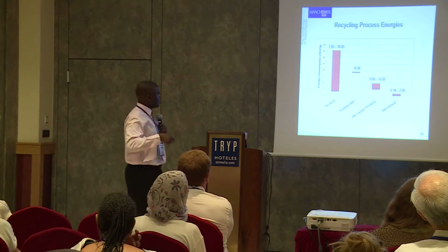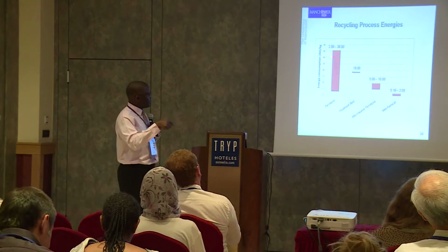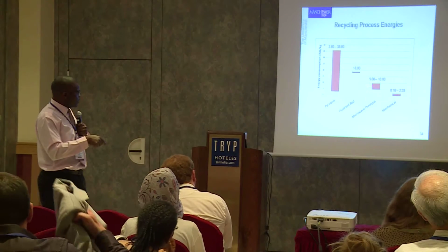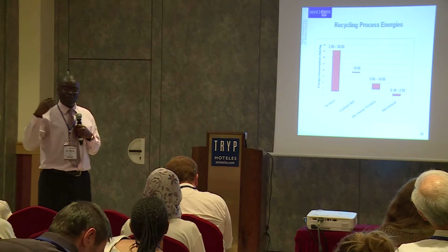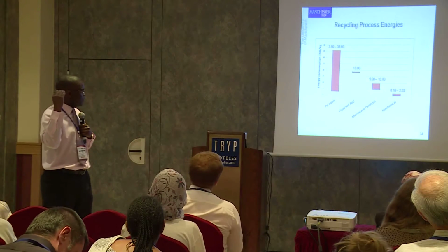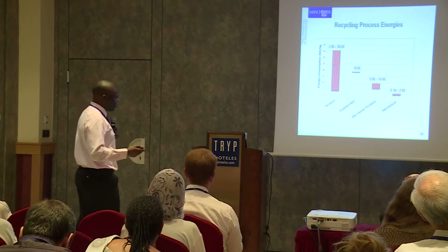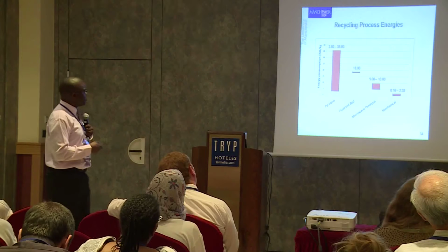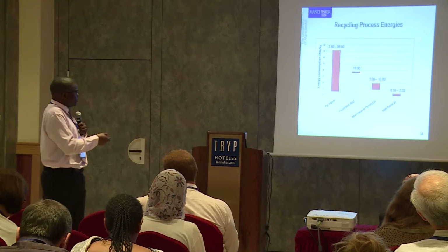So if I revisit all the processes before, mechanical, microwave pyrolysis, and then the conventional heating is very energy intensive. So we're interested in microwaves here because not only is it energy efficient, but there should be a benefit, because if you're not putting a lot of energy into the fibers, you're not damaging them. So if you can design a process which is energy efficient, it means what you recover is actually high value. So there is a collateral damage associated with energy input into materials. So we are looking at that and how you can, if we can optimize this and bring it down, we should be able to get better fibers.